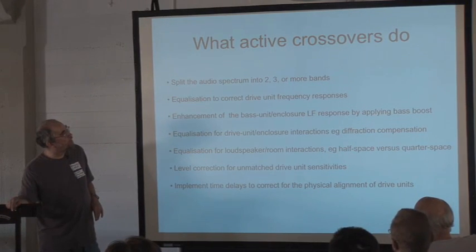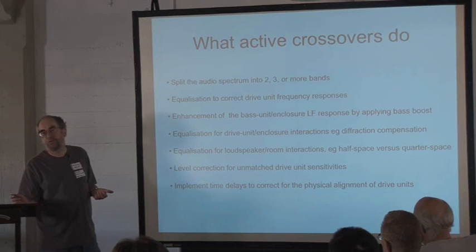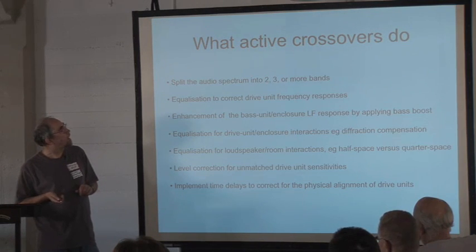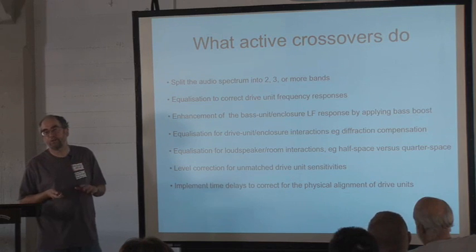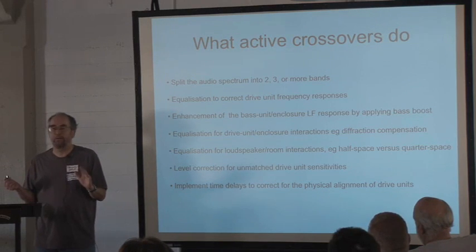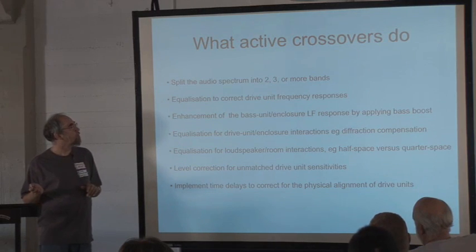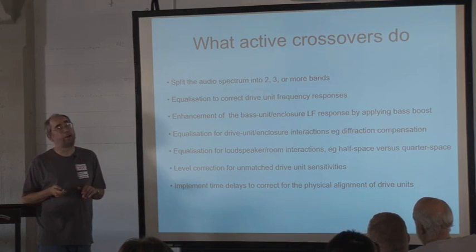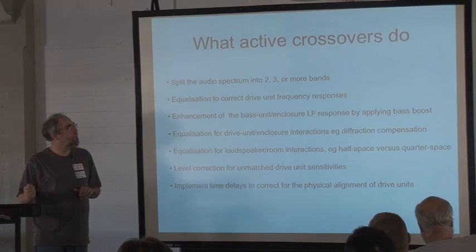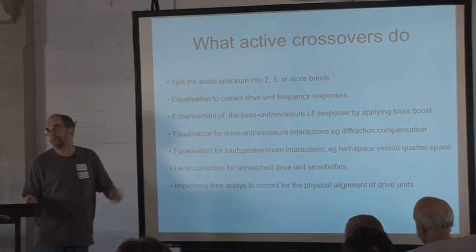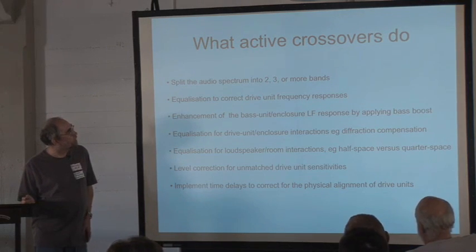You can add equalization to get the drive unit response to fit in with your crossover scheme. Now that's a little bit more complicated because you've got to work out how accurately you can get that, and how much variation you've got in your drive units. Trying to equalize a drive unit to 0.1 of a dB, you really are wasting your time. The next one will be a dB off. So that's something you have to think about quite carefully.